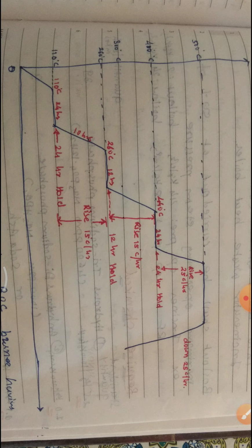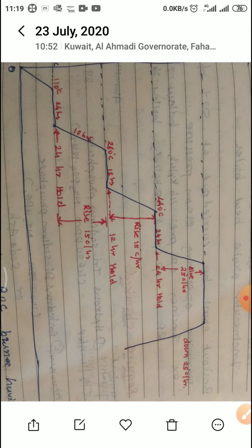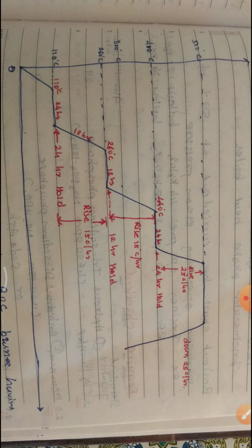When alkali boil out finishes, start the rinsing. Why is rinsing required? Because initially we added chemicals, and all chemicals should be removed. That's why rinsing is required. During rinsing, CBD and IBD are given at full flow and the drum level comes down to 40%, and again is filled up to 60%. These steps are required 2-3 times.